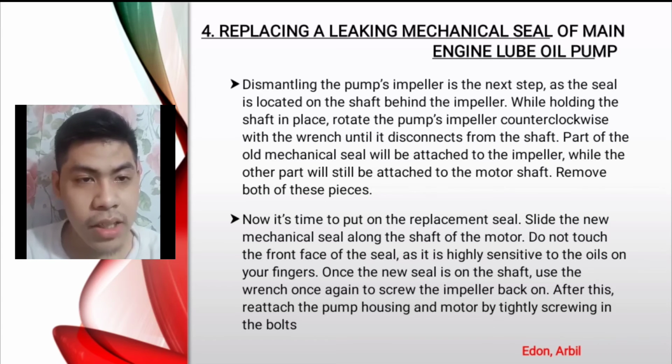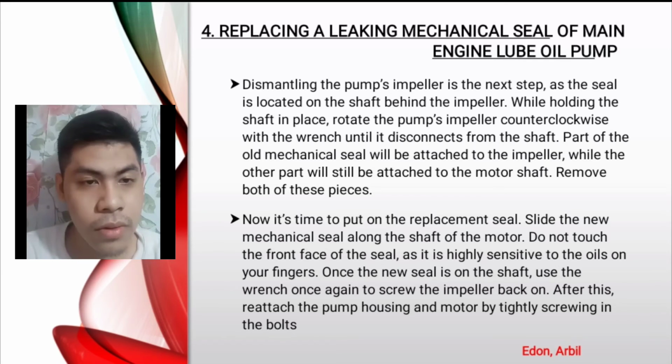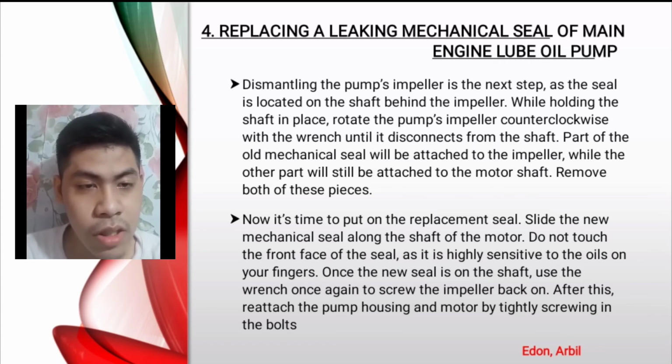Slide the new mechanical seal along the shaft of the motor. Do not touch the front face of the seal, as it is highly sensitive to the oils on your fingers. Once the new seal is on the shaft, use the wrench once again to screw the impeller back on. After this, reattach the pump housing and motor by tightly screwing in the bolts.